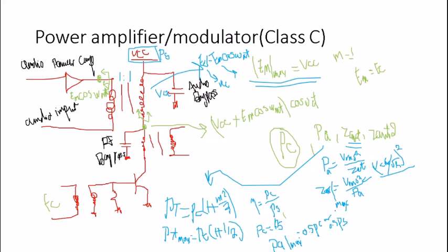But we found right here that the power of the amplifier is only 0.5 multiplied by the power of the supply. But the power of the supply right here is only VCC multiplied by the current that comes out of that supply. So to make it all into a simpler form, by taking the square root, we get VCC squared, and then 2 square root squared, you get 2.